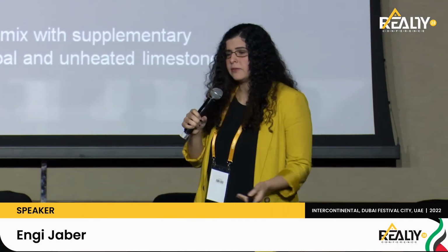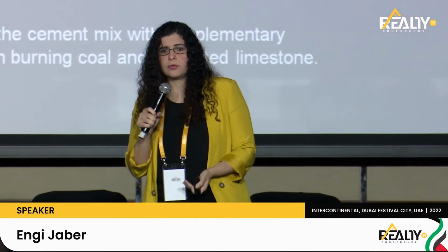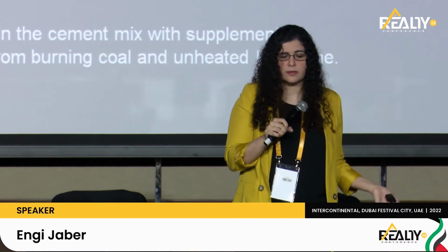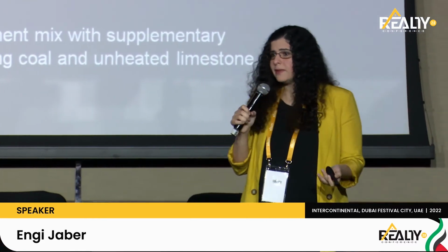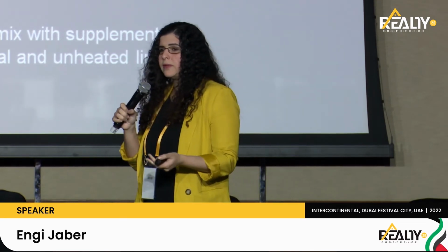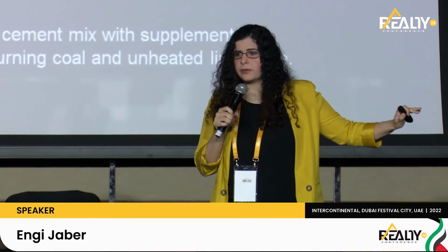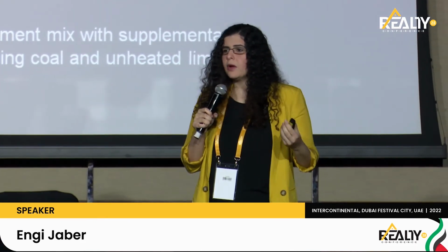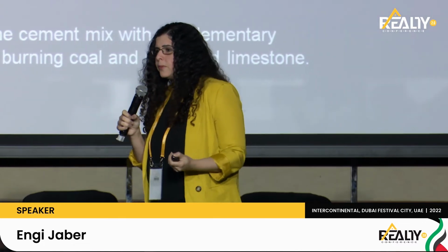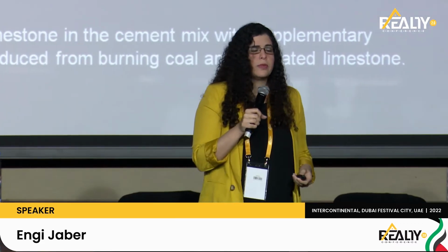Other manufacturers, and this is more commonly used, especially in this part of the region, and it's actually part of government legislation, use SCMs, which are supplementary cementitious materials, such as fly ash or any other materials. The reason we use that is that we are trying to steer away from limestone in the production. So it reduces the carbon footprint just by increasing the amount of fly ash or any other alternative within the cement composition.